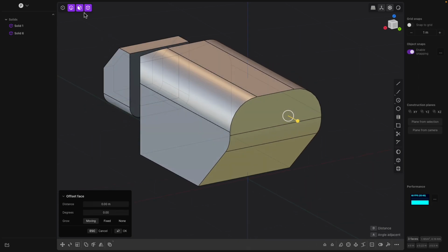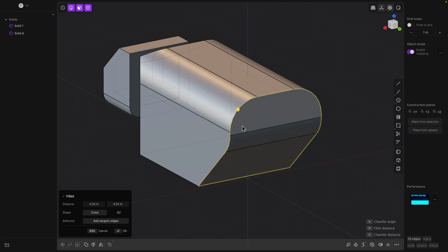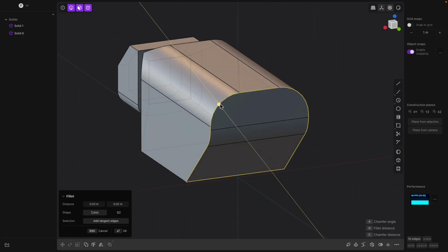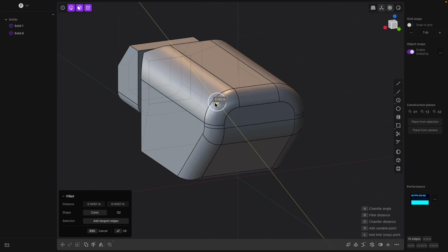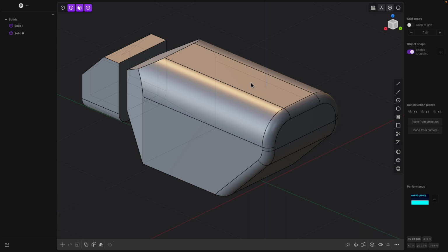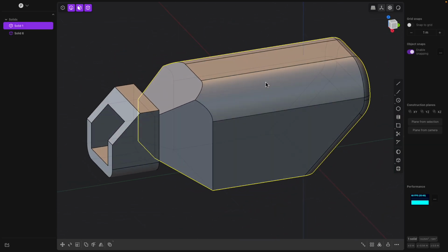You select the face, and then I was looking at this, and okay, convert selection to face, convert selection to edges. So Ctrl 2 switches that to edges. Now we can round the corner like that. So that's really pretty handy. Let me save this very quickly.